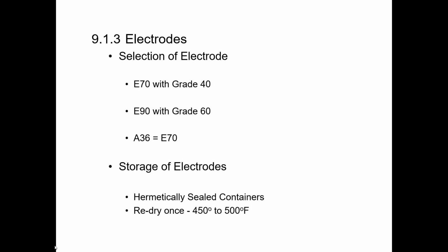In that instance, there's much more opportunity for that weld to fail versus a lap weld where you take two bars, lay them side by side, and weld a certain length of that lap. So the reason for the more stringent requirement, like having to use an E90 electrode, is because there's more opportunity for that connection to fail. So again, the slide, just like the way the book was printed, is assuming a full penetration butt weld, and that is just not something that's common.